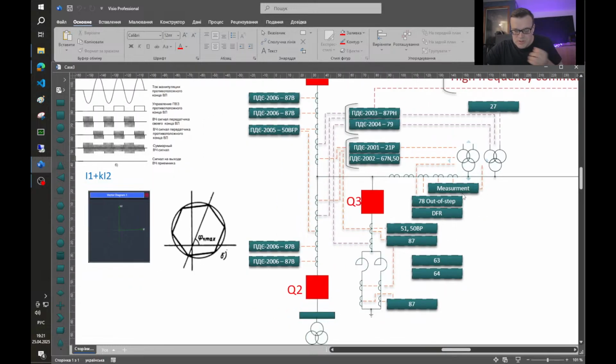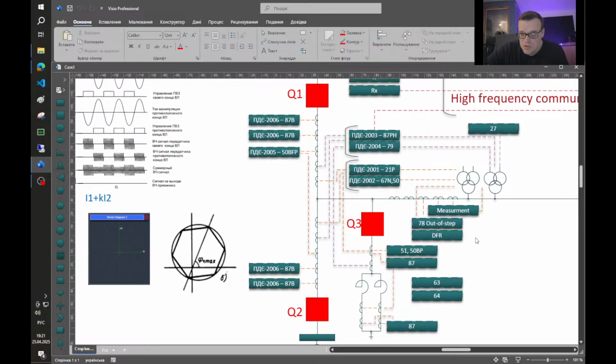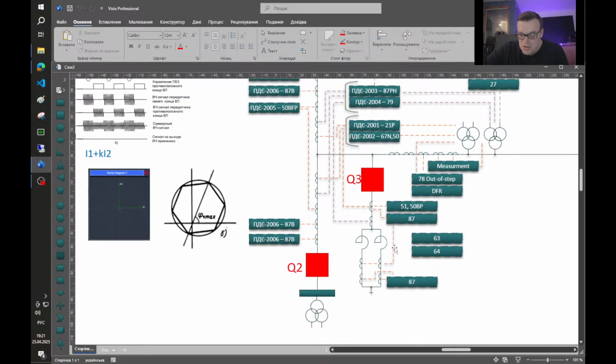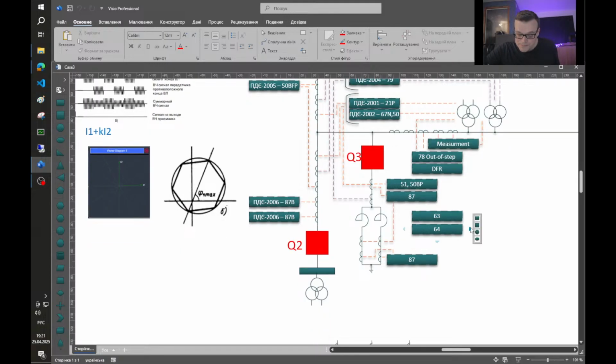What I want to say is that on a line, the CT is usually connected to the protection measurement. I showed here a digital fault recorder, but usually it is connected to all of the CTs. So the shunt reactor has an insulation monitoring system for bushings, and also a Buchholz relay.